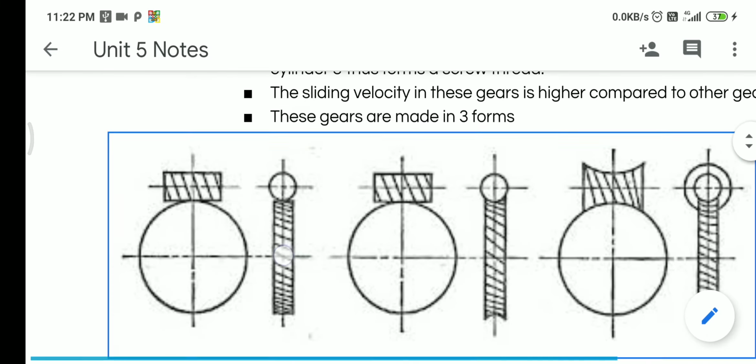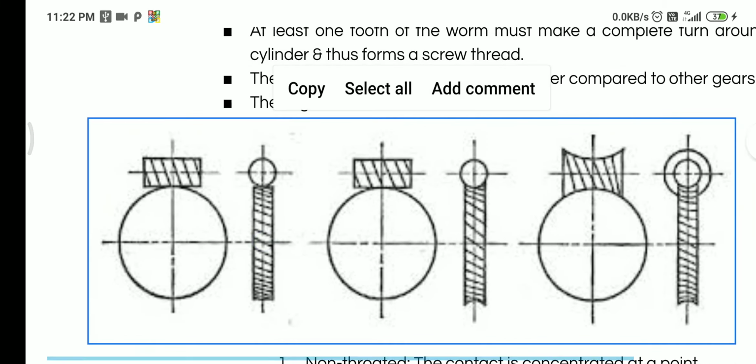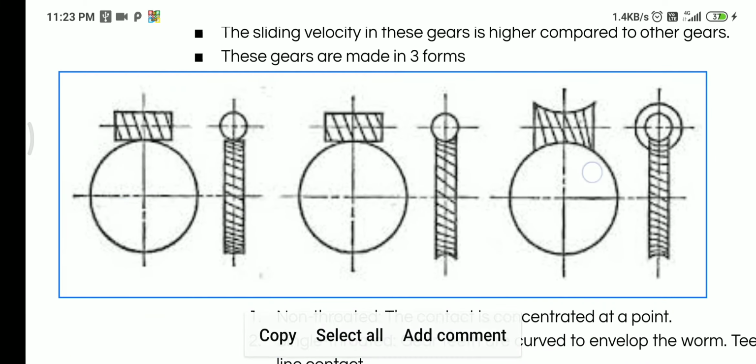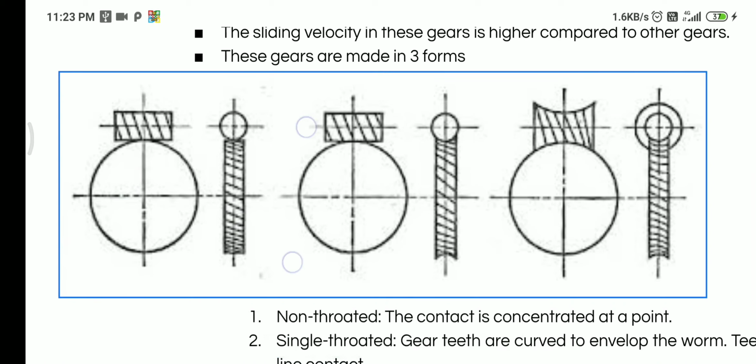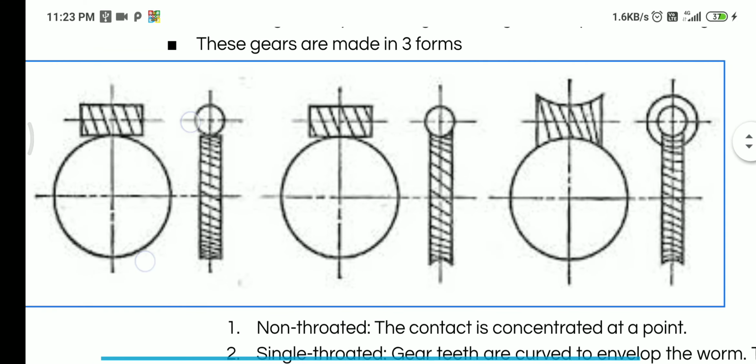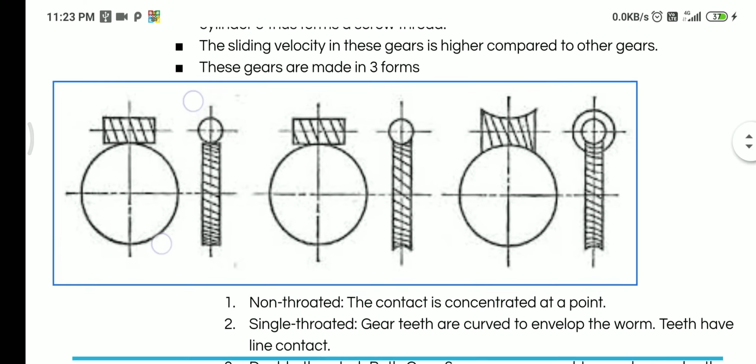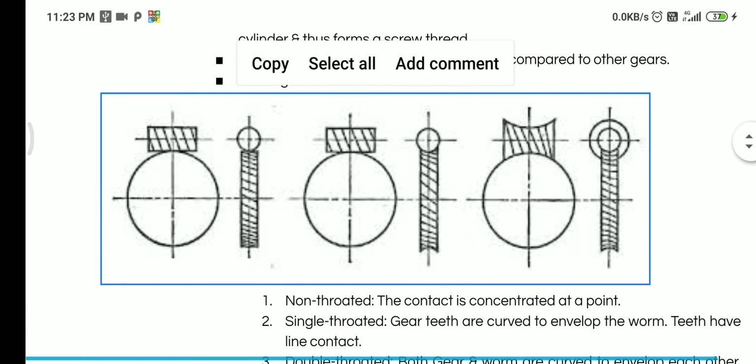But when you're looking at the efficiency of the gears, the efficiency goes down as we proceed from the left type to the right type, because there is more surface contact, and naturally the kind of friction that we have here is going to be lubrication type of friction, and viscous forces are going to come into action, and that will effectively increase the friction experienced by these parts.